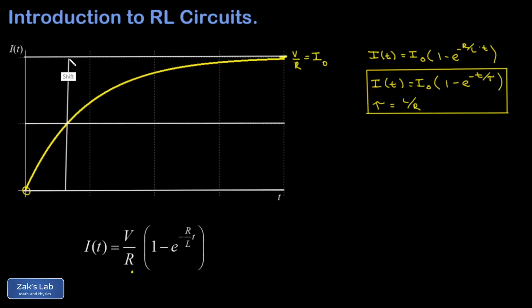Well, that means this time, the time from t equals 0 to the point where I gets to half its maximum value, that's the half-life, which we'll call t with a subscript of 1/2. To figure out what the half-life is, we look at our current function, and we say when t is equal to 1 half-life, I is equal to 1/2 its maximum value. In other words, 1/2 I naught. So to start the quick derivation, we just say 1/2 I naught, that's the moment we're interested in, is equal to this function evaluated at t equals 1 half-life.